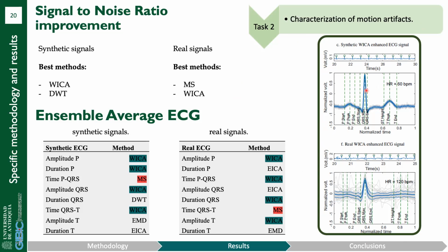I mean, I simulate an ECG signal without contamination and an ECG signal with contamination, and apply the denoising method to the signal with contamination, and compare the result of this signal with the reference signal, that is a signal simulated too, but without contamination.